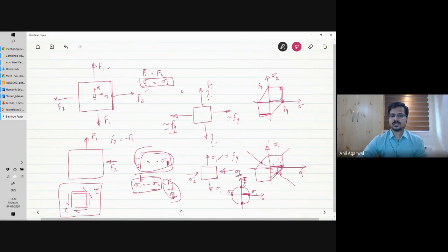Right? What it says is that the principal stresses are such that sigma 1 is equal to minus sigma 2, so tau and minus tau. And when they are equal to Fy by 2, that's when the yielding takes place, as per the Tresca criteria. We have just derived that, right?